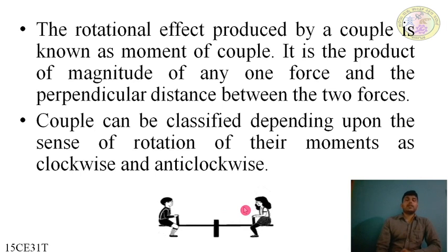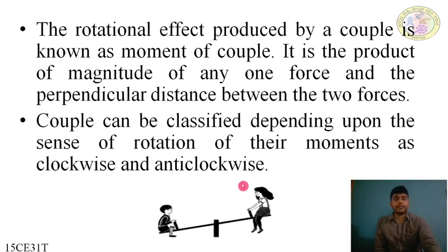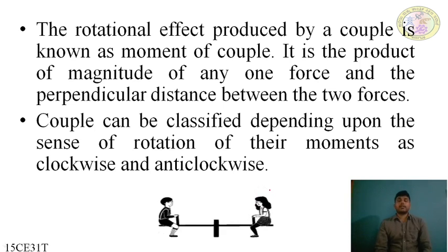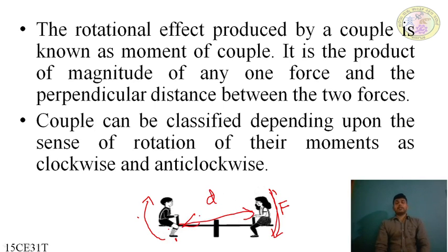Here also the couple is produced. He pushes with force from his left and it creates a couple here, and due to the weight it also creates a couple here, with a certain distance D between the two forces. That is how the couple is formed.